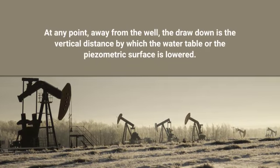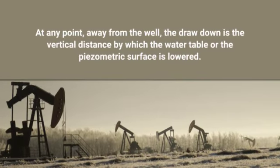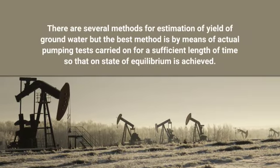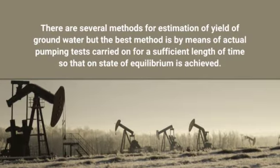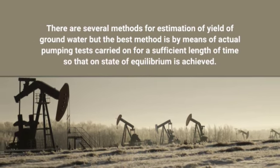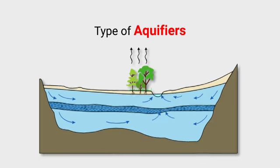At any point away from the well, the drawdown is the vertical distance by which the water table or the piezometric surface is lower. There are several methods for estimation of yield of groundwater, but the best method is by means of an actual pumping test carried out for a sufficient length of time so that a state of equilibrium is achieved.